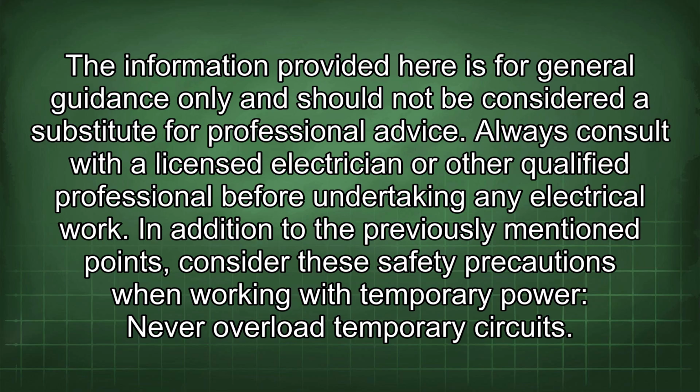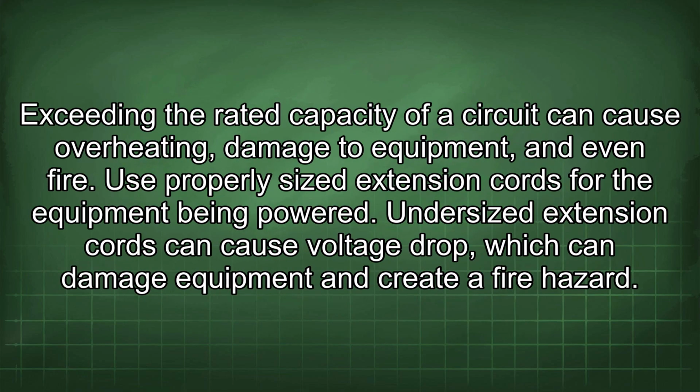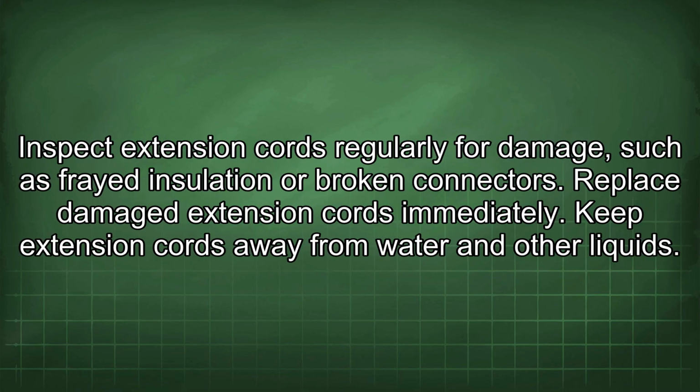In addition to the previously mentioned points, consider these safety precautions when working with temporary power. Never overload temporary circuits. Exceeding the rated capacity of a circuit can cause overheating, damage to equipment, and even fire. Use properly sized extension cords for the equipment being powered. Undersized extension cords can cause voltage drop, which can damage equipment and create a fire hazard. Inspect extension cords regularly for damage such as frayed insulation or broken connectors. Replace damaged extension cords immediately. Keep extension cords away from water and other liquids.